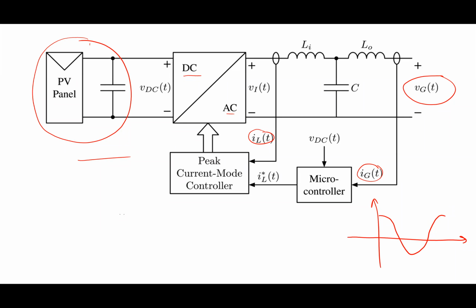Last time I introduced this idea and I said, where do we use this? We use this all the time. Very often what happens in the real world is I get a signal. I measure something, a voltage or a current, and I bring that into a microcontroller or something like that. I want to know what sine waves are in that signal, because I need to know that to potentially control something or to make something happen that I want to have happen.